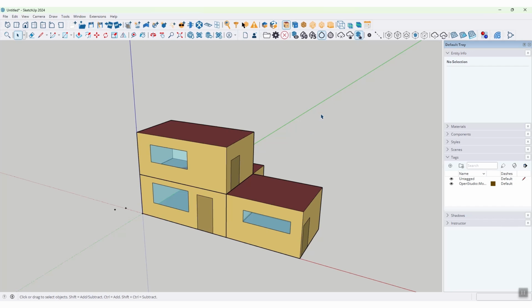One of the important modes is rendering the model based on surface type. This is usually the default display mode. In this mode, each surface is colored based on its type. For example, walls, roofs, floors, windows, and doors each have a different color. You are already familiar with this color scheme from the internal drawing tool in OpenStudio. This display helps us check whether the surfaces have been correctly recognized as wall, floor, roof, ceiling, window, or door.